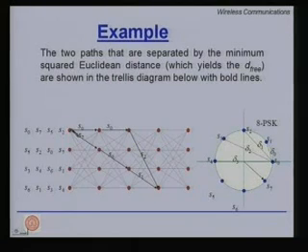Now, for the output bits, we do not send them, we map them back to one of the 8 possible 8 PSK symbols. So, in this example, 2 bits come into the convolution encoder, 3 bits come out, but each of the 3 bits is mapped to one of the possible 8 PSK symbols. So, instead of writing 3 bit outputs on top of the branches, we write symbols. So, for any 2 bits that come in, a symbol goes out. We have combined the encoder and modulator.